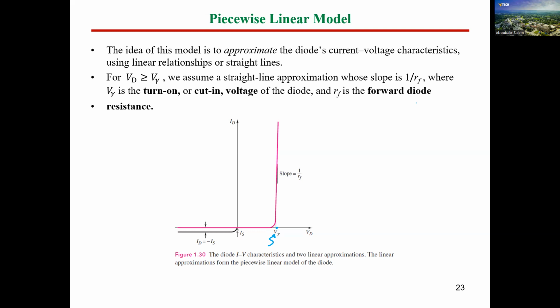By any means, guys, if you have a resistance and current is flowing in it, you will have some losses. You know that power across any resistance equals I squared times R. So we care about the equivalent resistance during turn on. We don't care about the resistance during turn off.